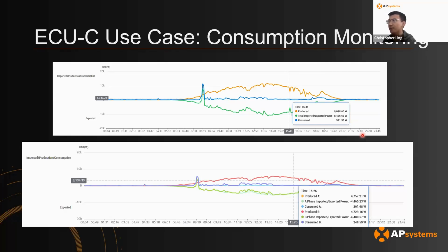One thing I will mention is that for three phase, that's not a problem to do. For split phase, it can get pretty complicated because it's really hard to export control a single phase microinverter when you have a split phase load. If one phase is consuming more power than the other phase, it's rather difficult for the single phase microinverter to adjust for that, because it only has control over the sum of both phases.